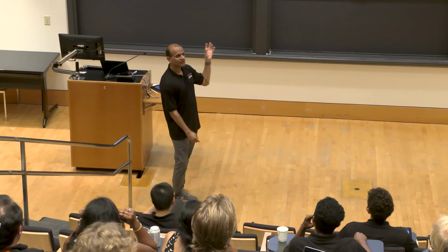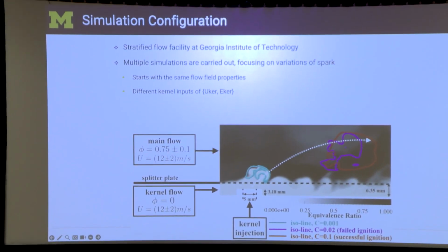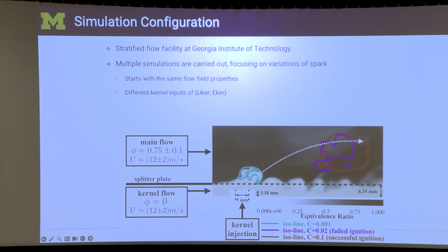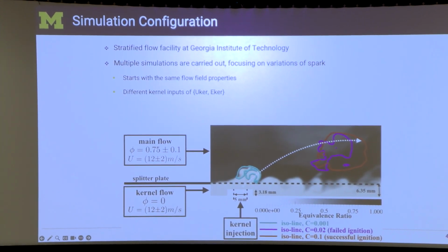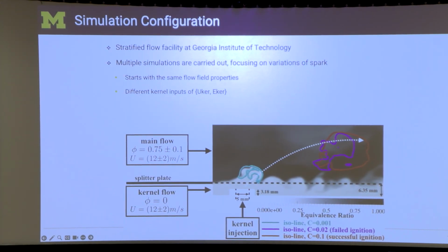So our solution is to take this geometry, come up with that new manifold for this particular system, okay? And then we run multiple LES calculations. Each time, we change the inflow turbulence properties. So it's a different starting condition, different initial condition. We also change the strength of the pulse.